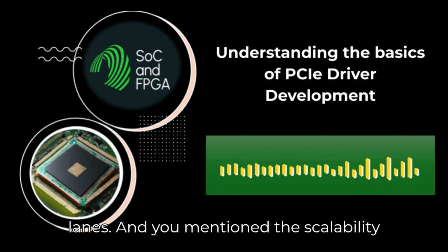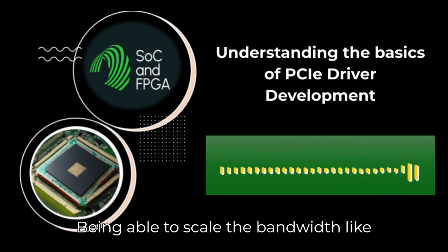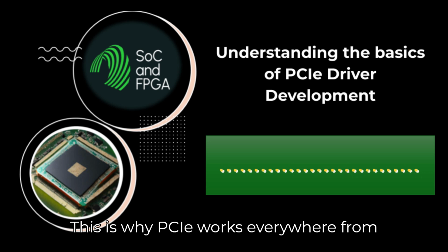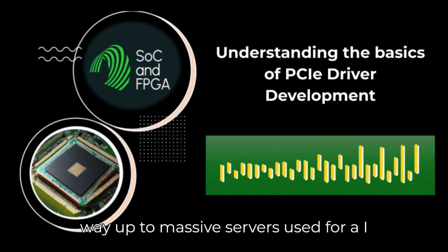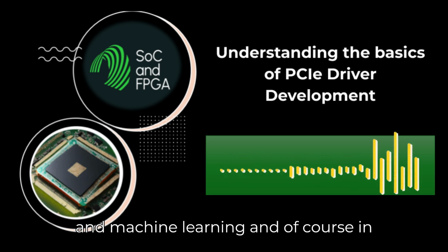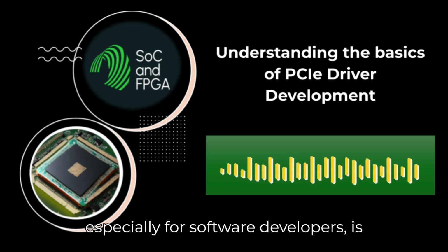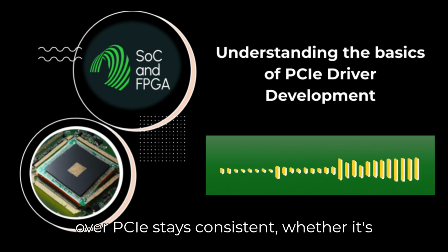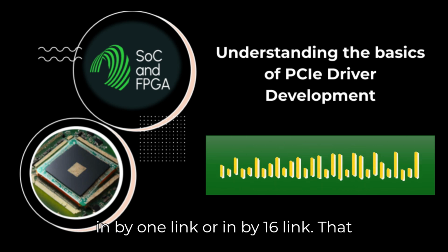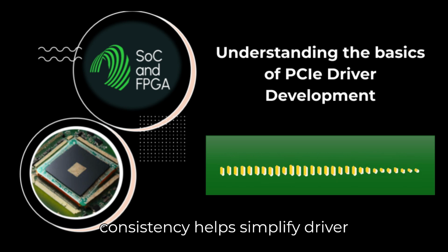And you mentioned the scalability makes PCIe very versatile. Absolutely. Being able to scale the bandwidth, this is why PCIe works everywhere, from tiny low-power embedded systems all the way up to massive servers used for AI and machine learning, and, of course, in your desktop PC. And what's interesting, especially for software developers, is that the basic way communication happens over PCIe stays consistent, whether it's in an x1 link or an x16 link. That consistency helps simplify driver development.